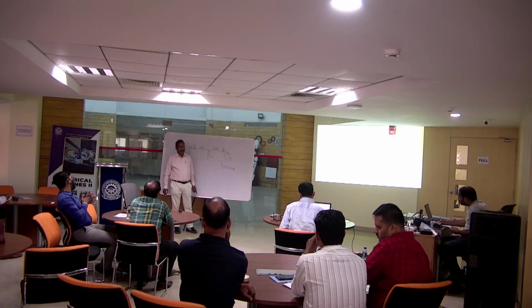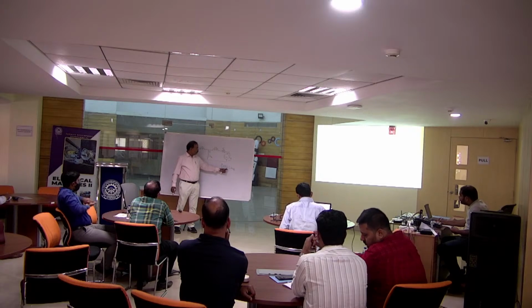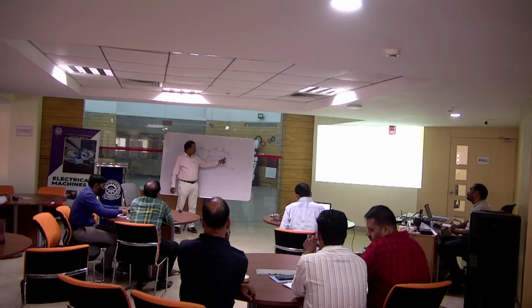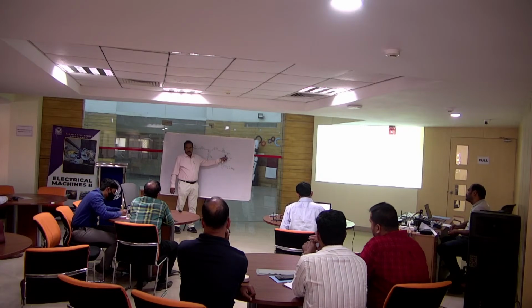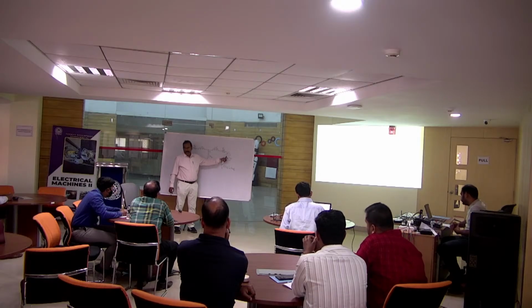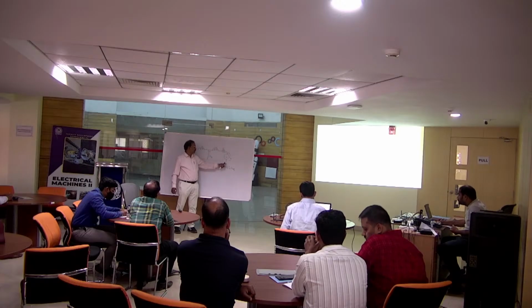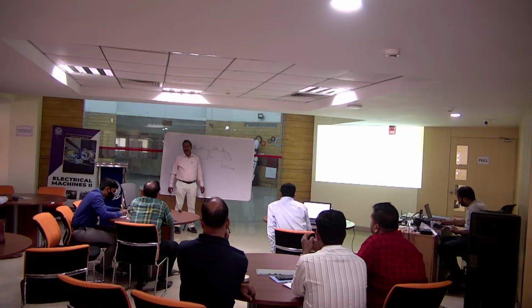This is the power. So now the power P2 is associated with this source in the slip ring circuit. Obviously these are the slip ring terminals. This is applicable only for slip ring induction motor. So depending upon the values of VR and IR, the power P2 can vary.